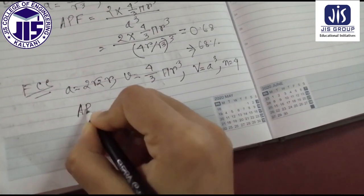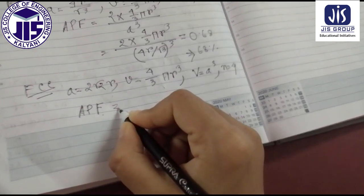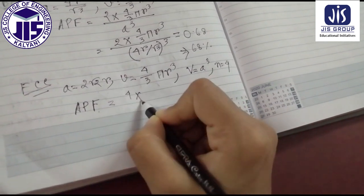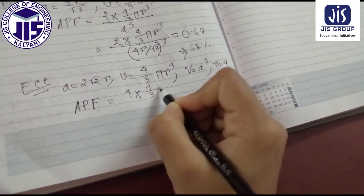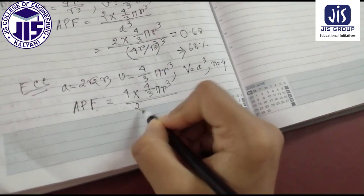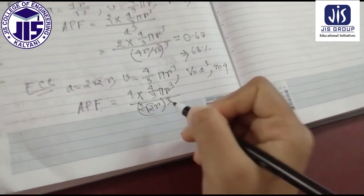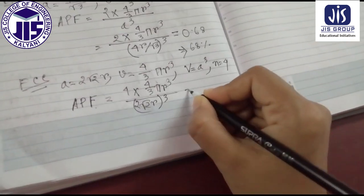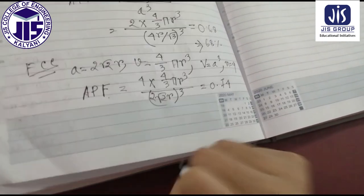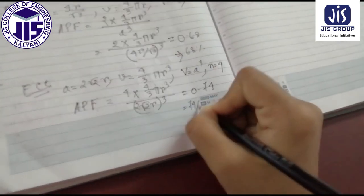Now APF, atomic packing fraction, is equal to 4 into 4/3 pi r cube by a cube. Here a means 2 root 2 into r, whole cube. So if we do this calculation, then ultimately we are getting 0.74. So the final answer is 74%.